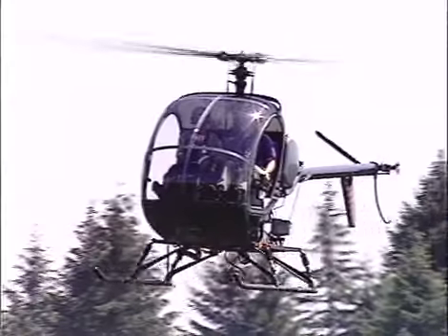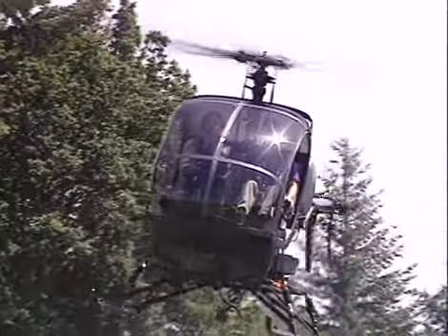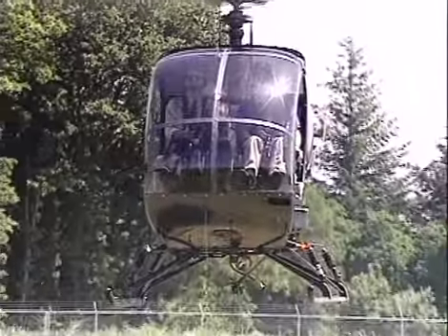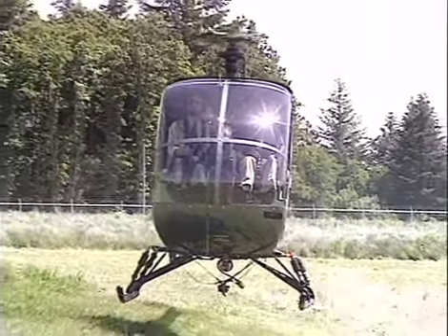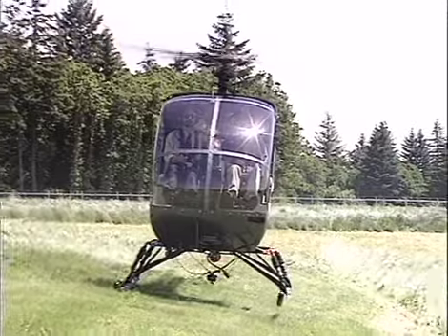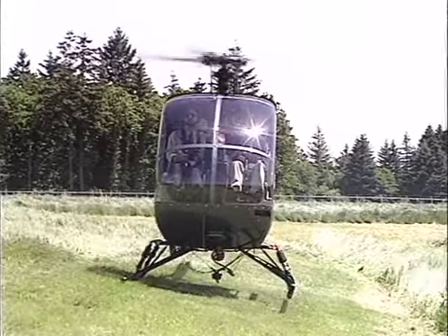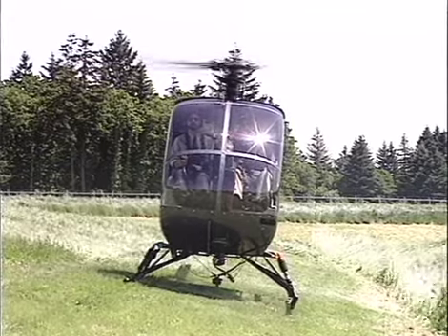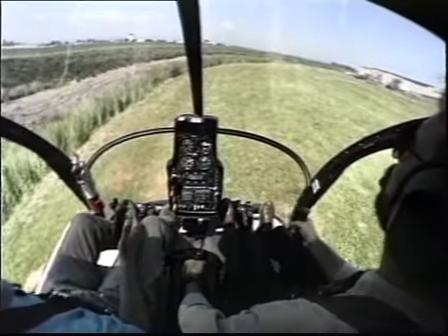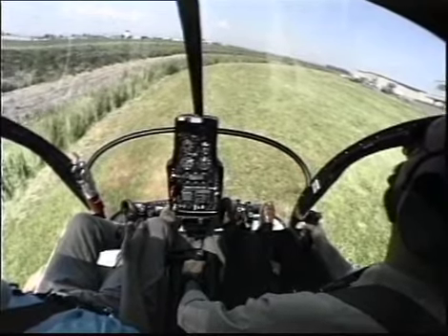Most people are not aware of it, but helicopters are not very good at dealing with sloping terrain. In fact, many students find slope operations among the most challenging maneuvers to learn in a helicopter. Under most circumstances, you should position the helicopter across the slope and into the wind for landing. When parallel to the slope, slowly lower the collective pitch to start a descent. As the upslope skid touches the ground, apply increasing pressure on the cyclic pitch control towards the slope to hold the uphill skid against the slope.